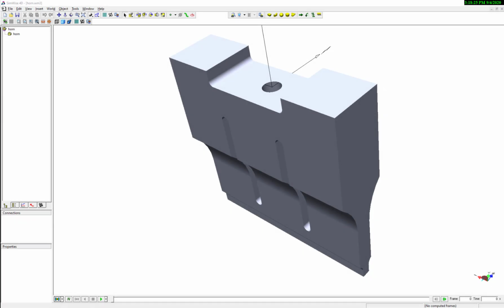This is a model of an ultrasonic welding horn, or sonotrode. It is the end part of an ultrasonic stack that transmits sound energy from an ultrasonic transducer into two parts that will be joined together at their connection via the absorption of sound energy. Ultrasonic stacks are tuned to work at certain frequencies, such as 15 kilohertz.